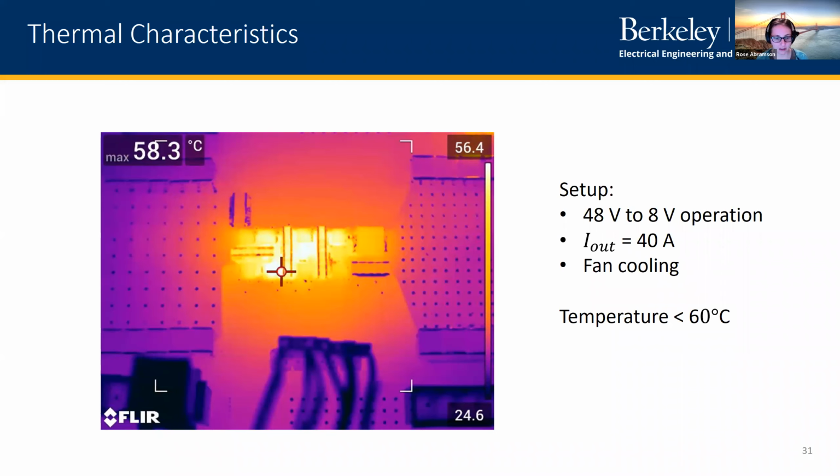And then you can see on the outside, there's wires and cabling coming in, but it's much cooler. And if you look at the FETs that are getting hottest, these FETs are not actually the ground reference FETs. So we don't think too much heat conduction is happening due to the large ground plane over the entire area of the board.